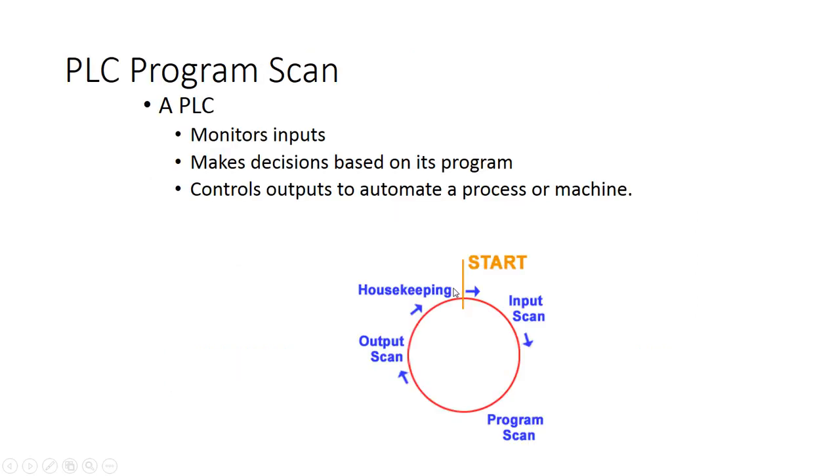So basically, a PLC, an SLC 500 second generation, would start by scanning all your inputs, all your switches open or closed. And then it would take a look at your ladder logic program. Based on your ladder logic, it would start closing or opening all the contacts or putting ones and zeros in there. We'll learn about the data table. So it takes the inputs and forces them into the program, and then it updates the outputs and writes those.